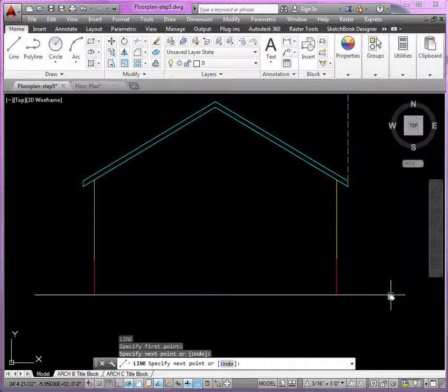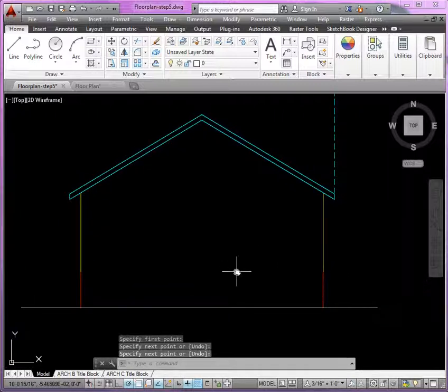And later on, once we finish talking about showing the details like the railings, the soffit, the stairs, we could start looking at hatching and color and pattern to really illustrate the materials that are being used for the finish. And of course, we could finish with annotations to show dimensions and show annotations. This is what we'll look at in greater detail in the following sessions.